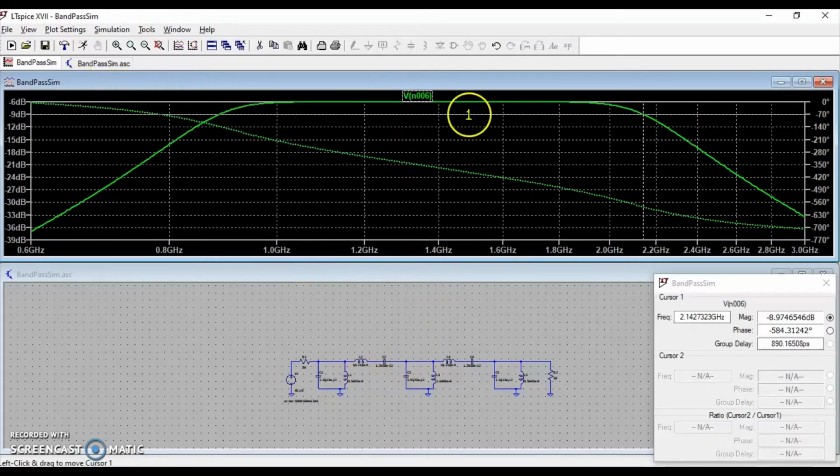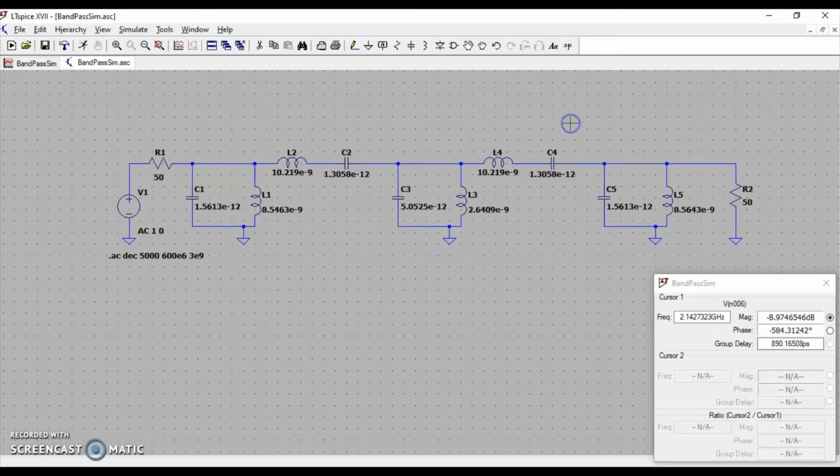To correct just the lossy nature of the circuit, there could be a buffer put in, other measures. But this gives a good framework for values when designing microstrip filters in ADS or other simulation software. Although this discrete component version, you can plug the values into ADS and use that. So just to recap, this is a turn-the-crank sort of method on building a filter for use either in discrete components or microstrip filters.